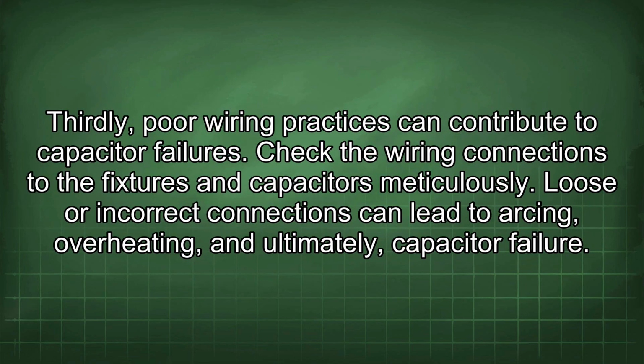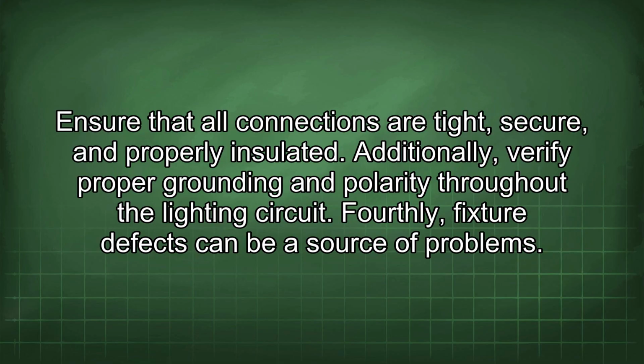Thirdly, poor wiring practices can contribute to capacitor failures. Check the wiring connections to the fixtures and capacitors meticulously. Loose or incorrect connections can lead to arcing, overheating, and ultimately capacitor failure. Ensure that all connections are tight, secure, and properly insulated. Additionally, verify proper grounding and polarity throughout the lighting circuit.